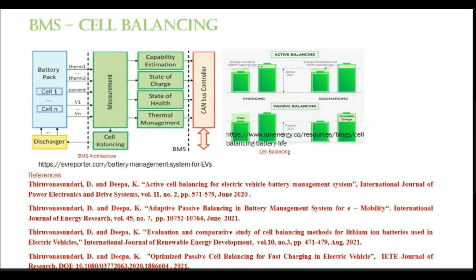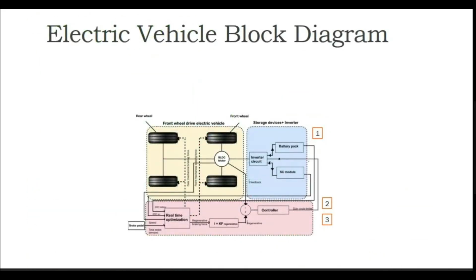And the same is being taken up for passive balancing. Initially, for the passive balancing, if the cells are new cells, then passive balancing was found to be better from our experiments. And if the cell is old, as it is aging, active balancing enhances its life more than passive balancing. So that was the conclusion of the thesis work of one of the students.